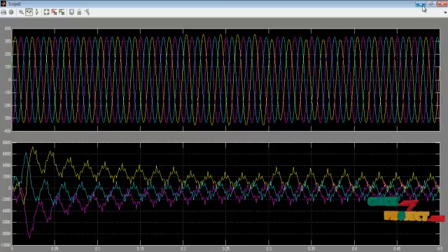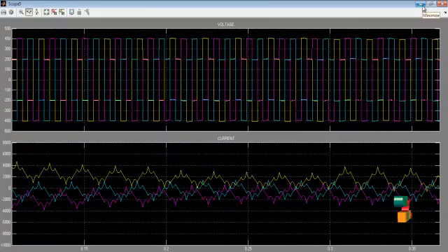Here we can see the voltage is 350 and the current range is above 6000 amps, and it reached 2000 amps before connecting to the grid side. So this is the voltage and current variation. Next is the inverter side output voltage and current waveform. Here the voltage and the current waveform are also high, 2000 amps and 400 volts.